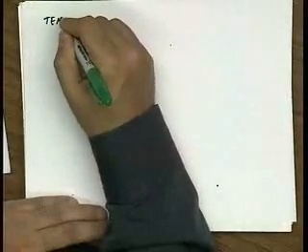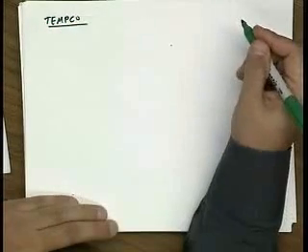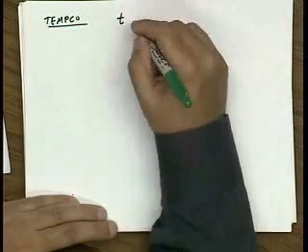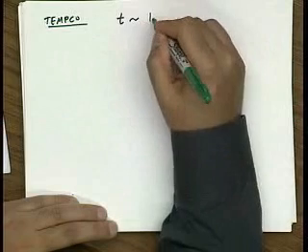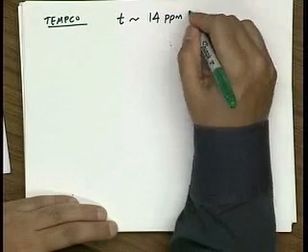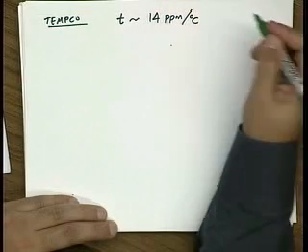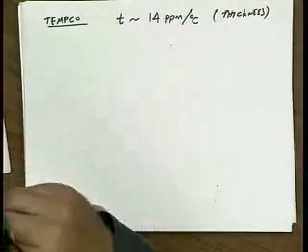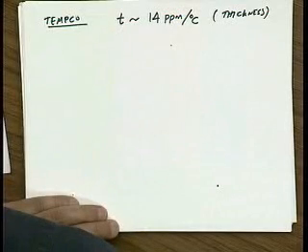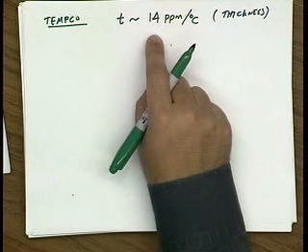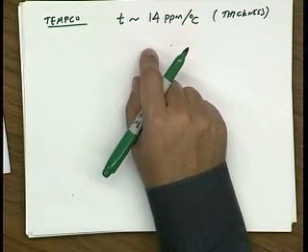All right, so how is the temperature stability of these crystals? Well, if you look at the thickness, it's a mechanical piece of material, and it changes thickness with temperature, about 14 parts per million per degree C. So if you just built a normal crystal oscillator, this would translate into your temperature coefficient. But it turns out that the phase velocity also has a temperature coefficient.